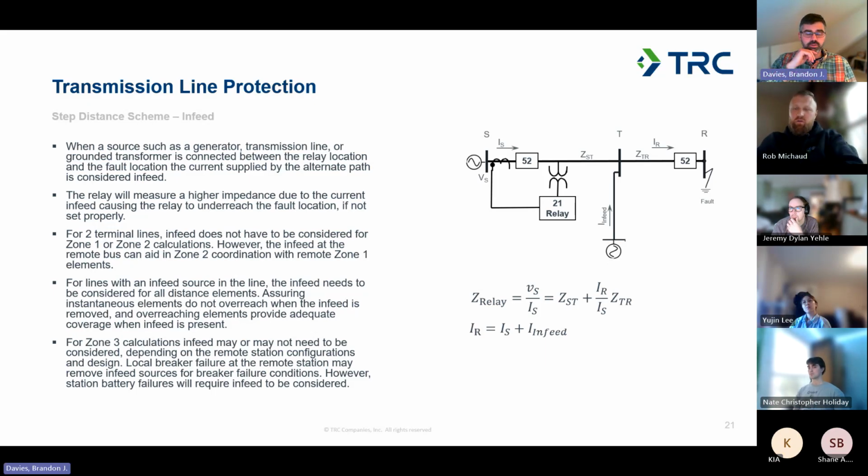No, they do. If you have a long transmission line, they will transpose the conductors so they're in different orientations. You've got your three conductors oriented like this, and they'll have a structure where the conductors go up to it in one orientation, and then they'll cross over and go in a different orientation to the next tower.